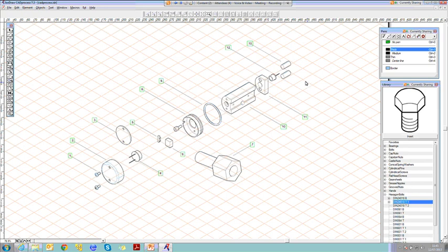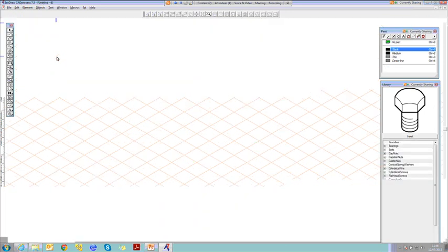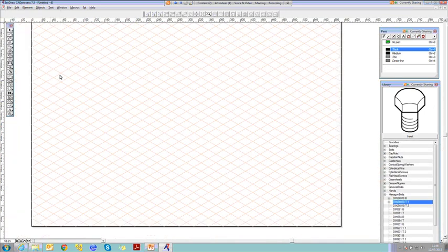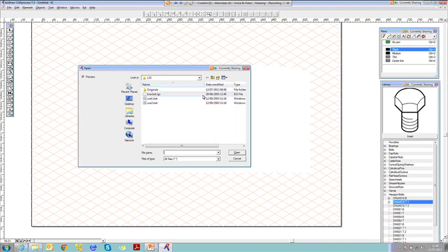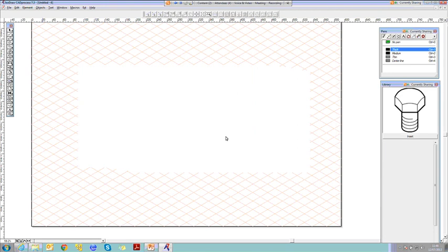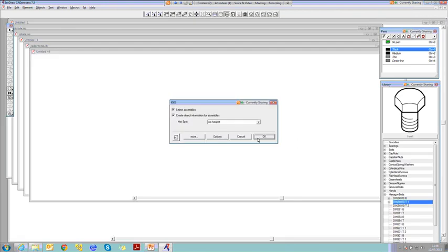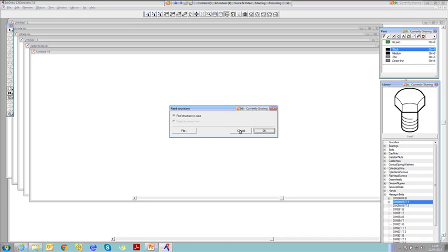In addition to that, if you then want to take 3D CAD data that has a change made to it, IsoDraw enables you to work with that as well. So now what we're going to do is create another new file, and we're going to go place and assembly. Here I have an IGES file, and we're going to place our IGES file. And again, it recognises that it's an IGES file, but it has some assemblies. Do we want to select those assemblies and filter out the information?